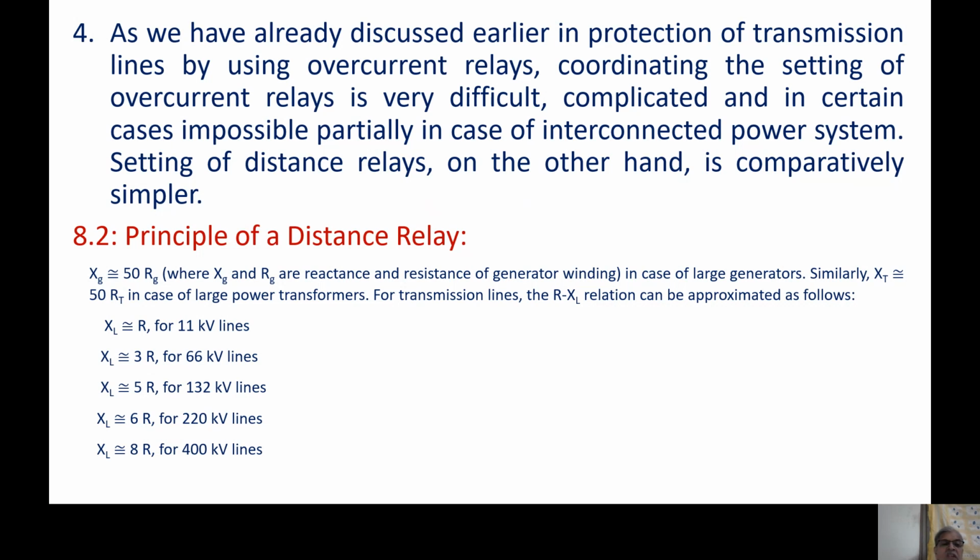But that steady state reactance may be as large as 50 times Rg, the resistance of the generator. The generator is highly reactive. Similarly, for a large transformer also, Xt is more or less equal to 50 times Rt.